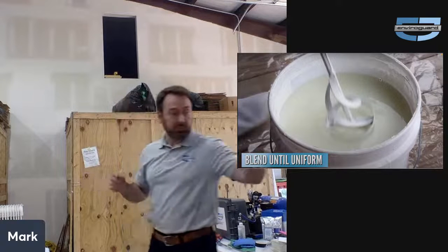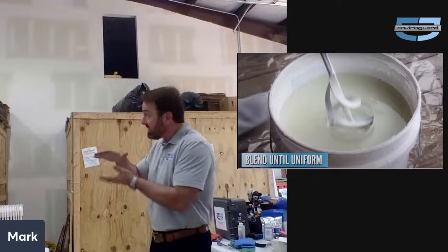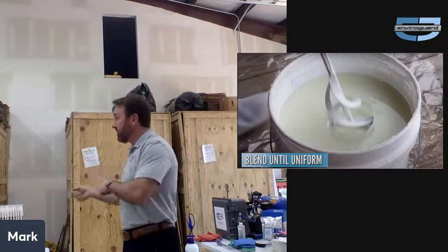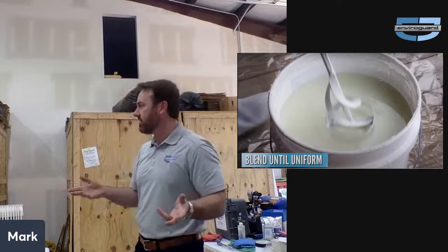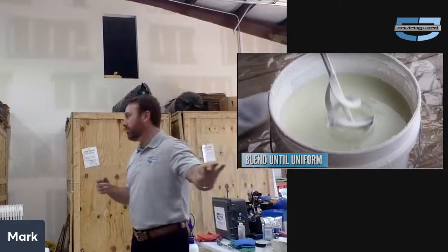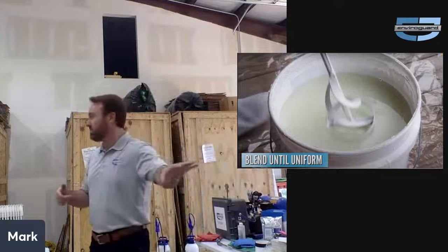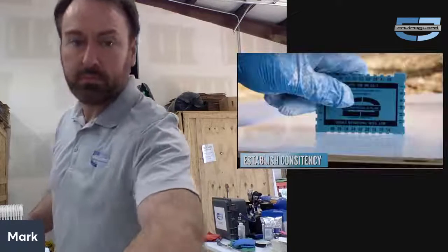Even if it's perfectly blended, as a coating sits in a bucket, it actually gets thicker. And when you blend it, it breaks that surface tension so you don't cavitate your pump. Because you could go, why isn't this thing priming? Well, the reason is you just didn't take a moment to blend that and break that surface tension. Literally, that surface tension gets broken in 10 seconds.